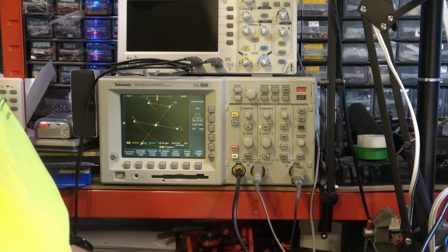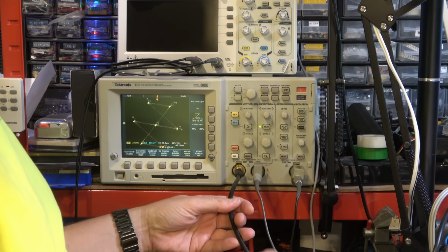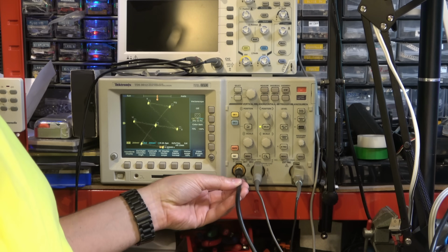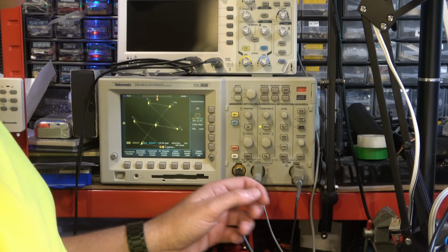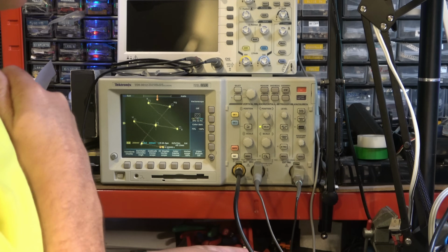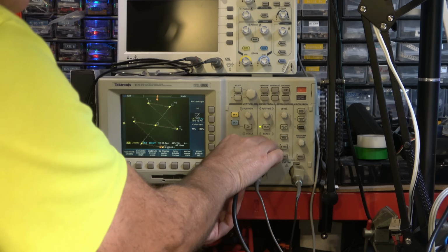What do you think I've got wrong? Of course, one thing that could be unhelpful is we've got a direct BNC connection here. We could have an impedance mismatch on that. I don't think that's the cause, but I suppose I could put the oscilloscope probe into the BNC socket. Yes, let's try that.